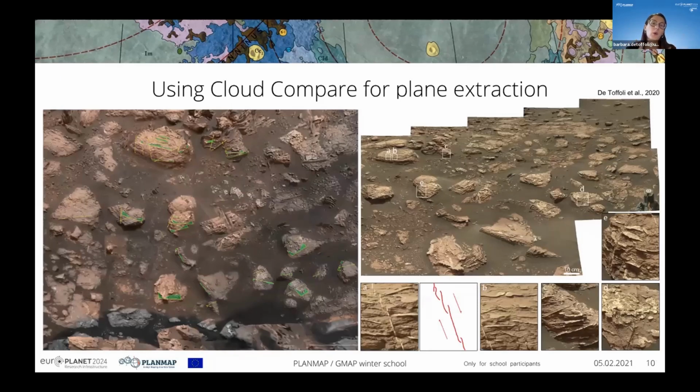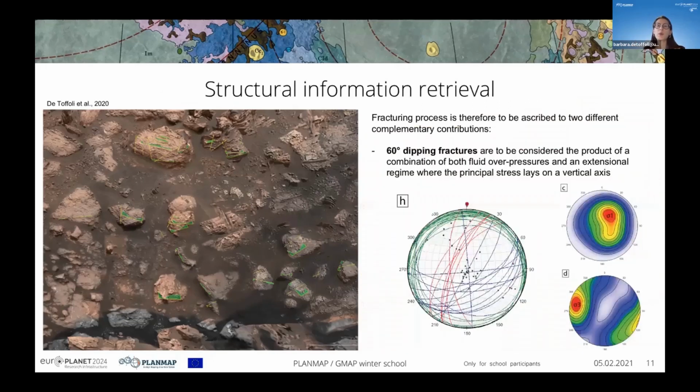but by itself, it's very hard to give quantitative information just by having this kind of representation. We needed something that could be easily visualized, also because these are just part of the knobs, and it was very hard to have a glimpse of everything with just one visualization. We needed to move around our mesh. So we decided to plot everything on a stereo plot, which looks like that. This means that basically we put all the planes we were able to map together and plotted them on a sphere. I think you will see in more detail how to build one afterward.